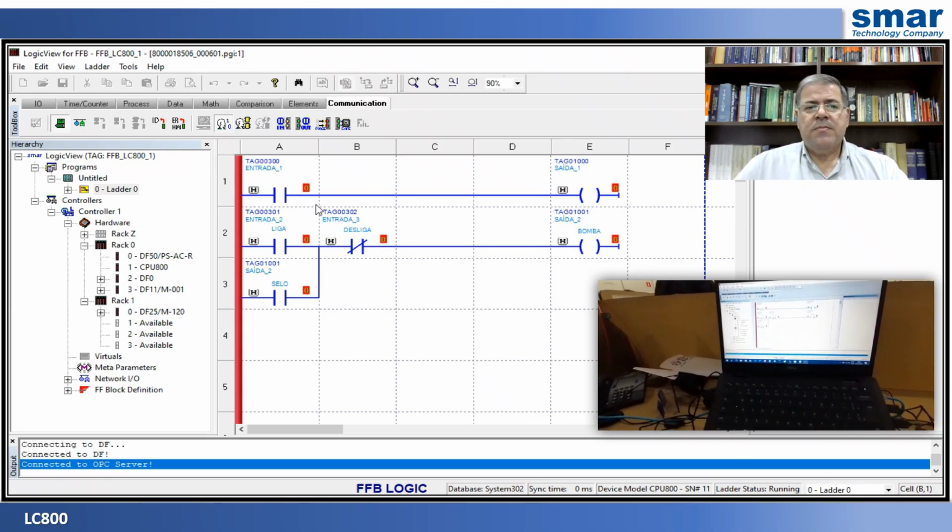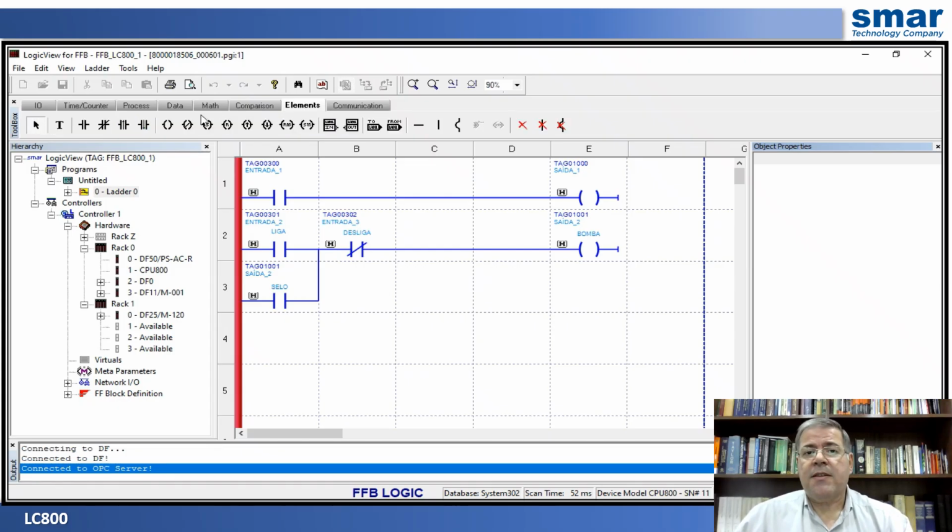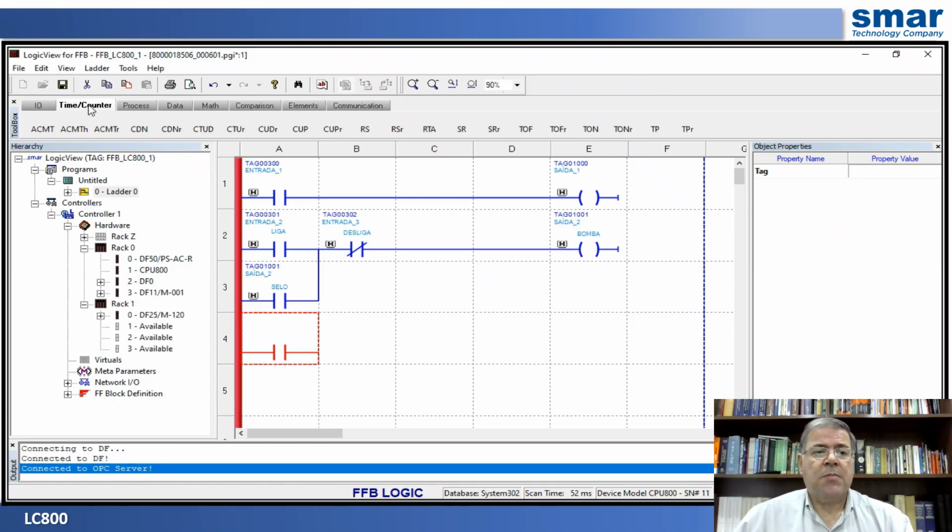That done, we were able to check the operation, and in the event of maintenance, monitoring our sensors and our outputs. Let's now add a new line and see how easy it is to make a new download, a modification to the project. So we add an open contact.